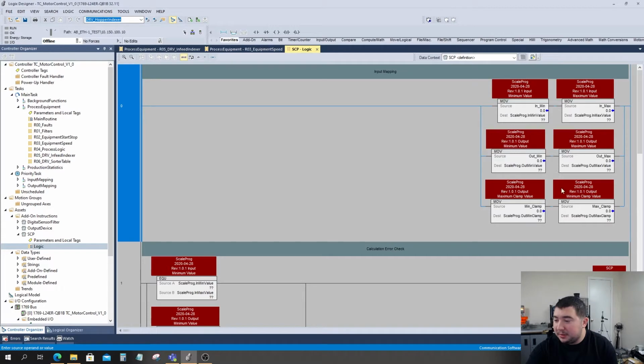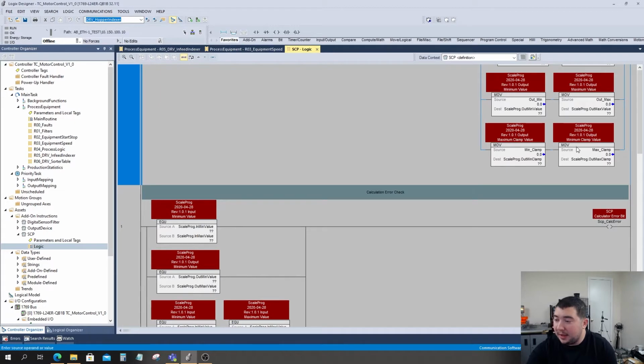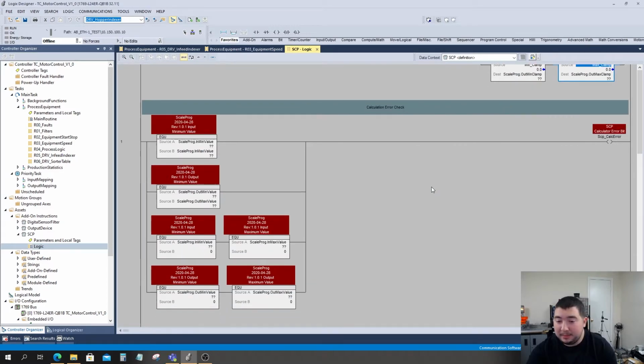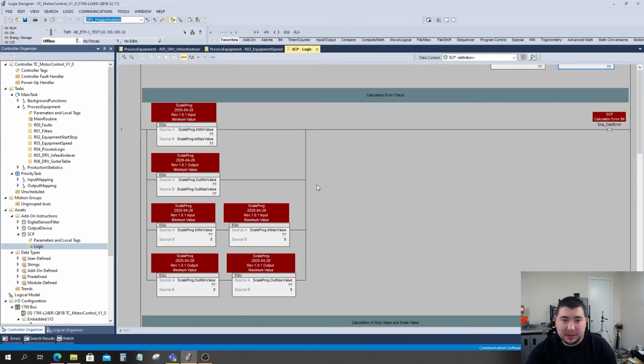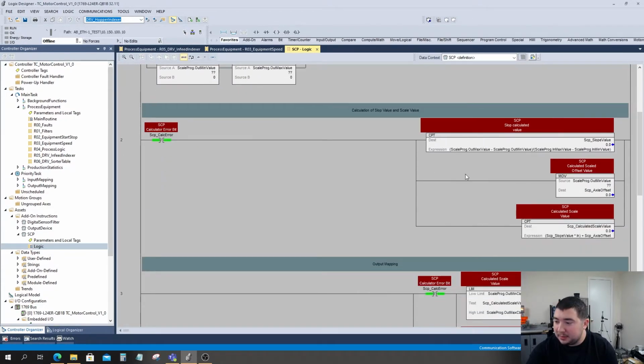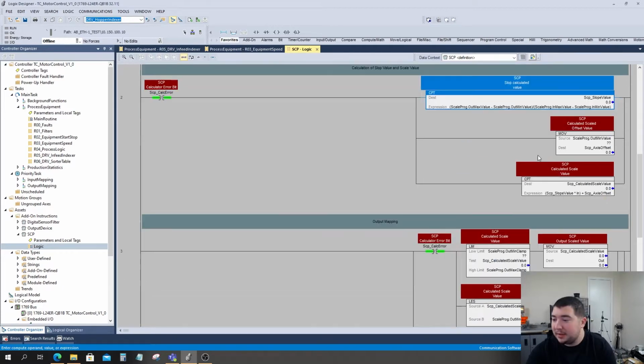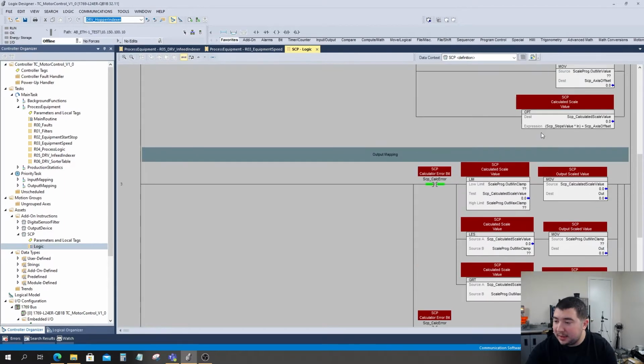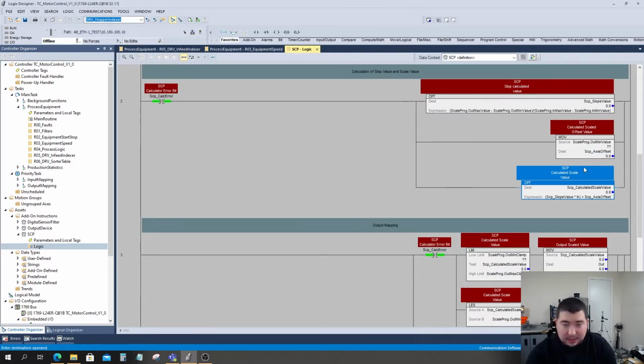So you enter in your input min and max, your output min and max, and I made it a little bit more intelligent where I could add clamp values so I can pinch off the value in the software rather than having to do that within the card itself. It does a simple error calculation so we can prevent things like divide by 0 instances and anything like that. And then we do the y equals mx plus b formula. The first thing we do is figure out what our slope is. And the next thing that we do is take that slope value and compute our output.